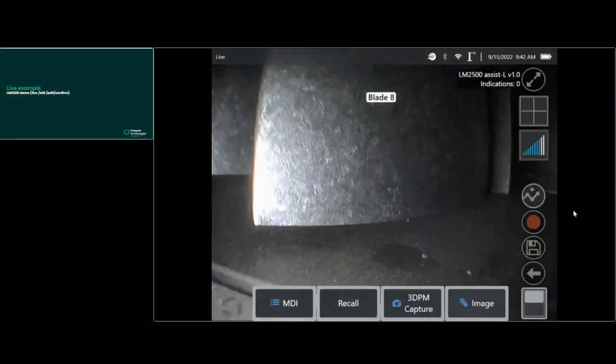So as you're doing the inspection, by all means have that feature turned off. We have the toggle there available to you, the users, because if you were to nudge and change the position of the borescope in relation to the blades during an inspection, by having those re-illuminated on the screen, you're able to reposition that borescope and continue using the blade counter. So it is currently necessary to ensure that the probe is fixed in position. So using the blade counter and setting it up and operating it is done once you're happy with the view and you're happy to do that rotation within that field of view.